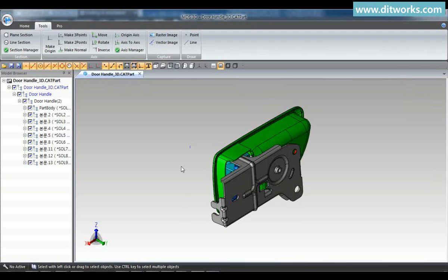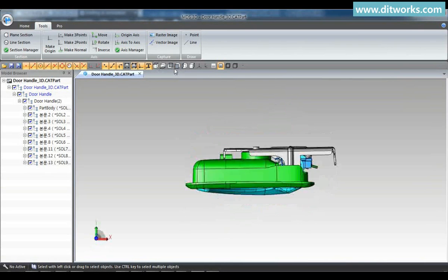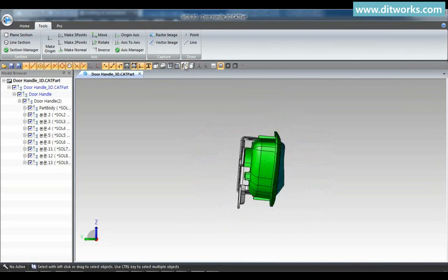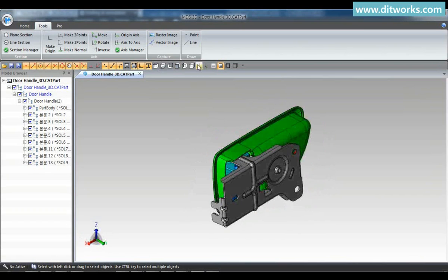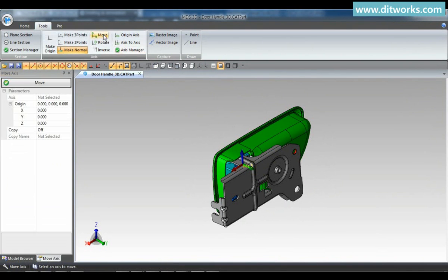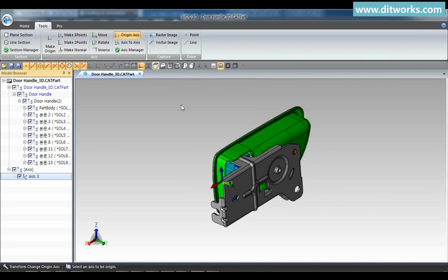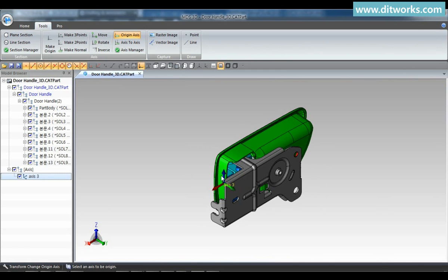The next step, I create a new axis and change the origin of the shape using the axis. Make a vertical axis of the plane, and move it. It is also possible to position any axis made. Especially, it is possible to change the reference axis of a shape that is inclined, to set a new direction of origin and shape.